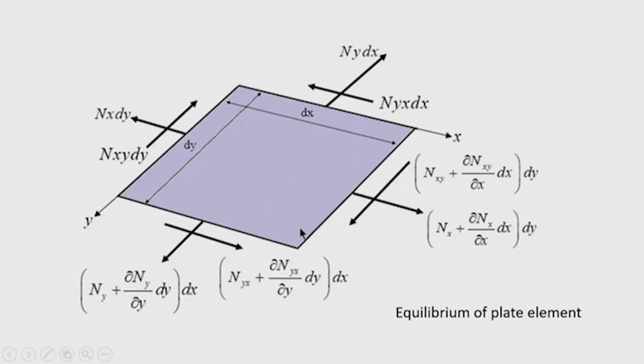Similarly, in this case, here you will get the resulting force is tensile. Okay. So, along one diagonal this is tensile force, and along the other diagonal there will be compressive force. Okay. So, the plate is under the action of in-plane direct forces and in-plane shear forces.